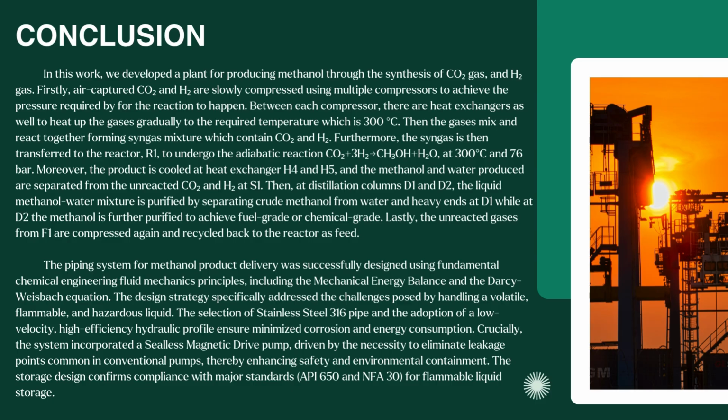The piping system, built with stainless steel 316 and a sealless magnetic drive pump, ensures safe, efficient methanol transfer while meeting API 650 and NFPA 30 standards.